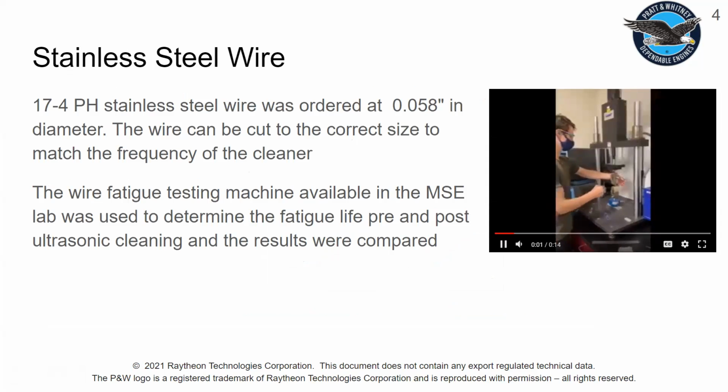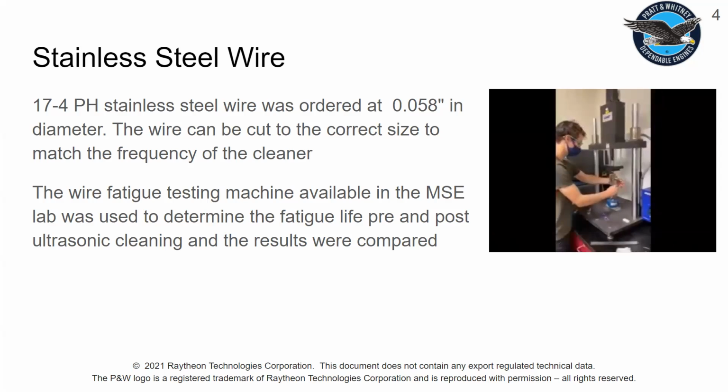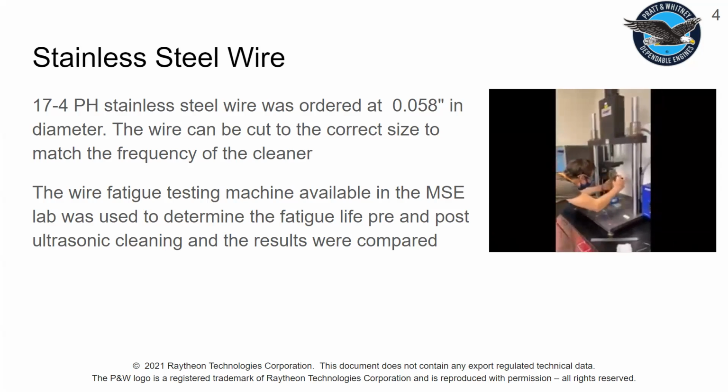So in order, our sample, we cut it to a length that would match the frequency calculated for our 34,000 hertz ultrasonic cleaner. We utilized a wire fatigue testing machine in the MSE undergraduate labs to conduct low cycle fatigue testing at controlled displacement.